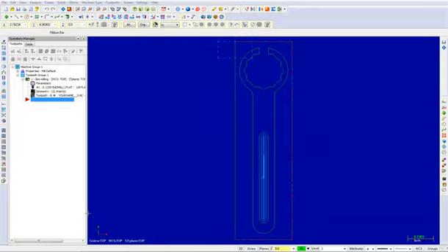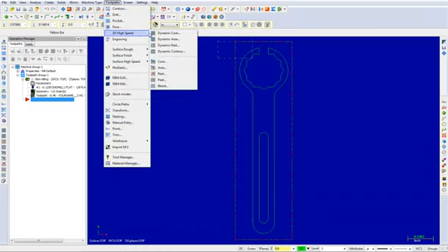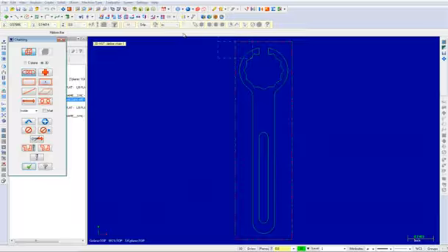First, remove the toolpath display from your screen. To do this, press Alt-T on your keyboard. Now select Toolpaths, 2D High Speed, Dynamic Core. When the chaining dialog box appears, leave the default settings as shown. Select the following entity. Once complete, choose the OK button to exit the chaining dialog box.